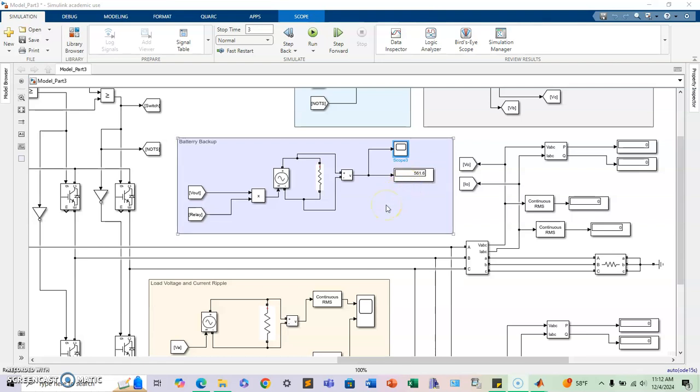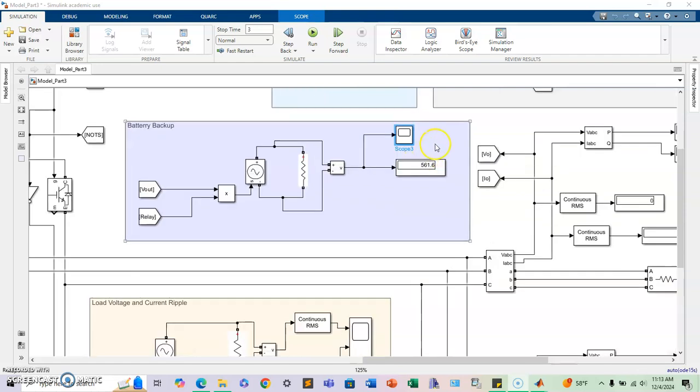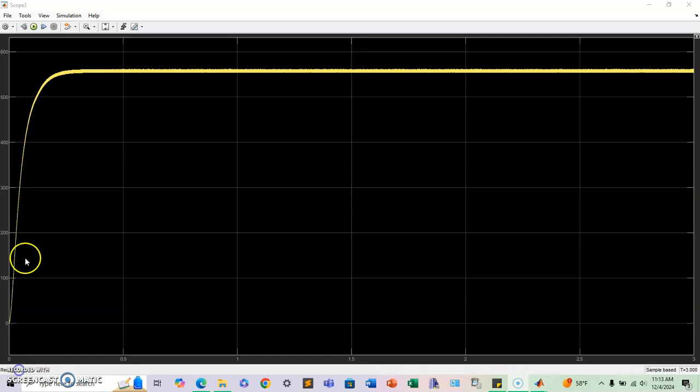But in real life, what you could do is use this battery backup, so the threshold will be those 350 volts, which is not ridiculous. It's less than half of the 800 volts, which is something that would happen on the PV side. The thing is, right here, I can simulate how the battery backup will look. This is the scope that I have.